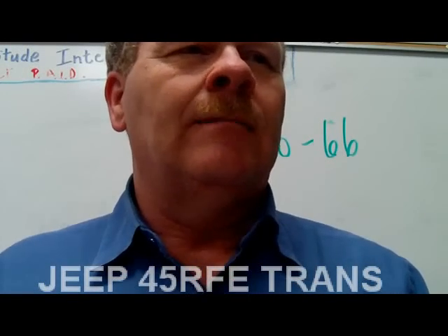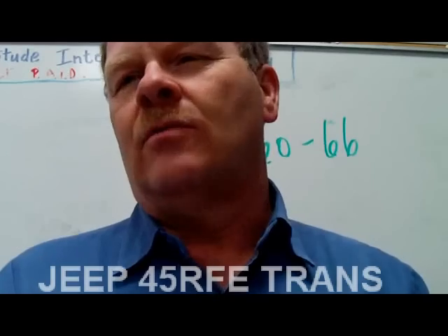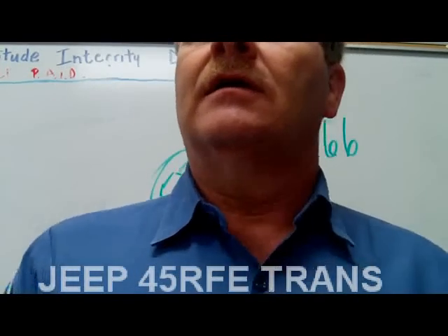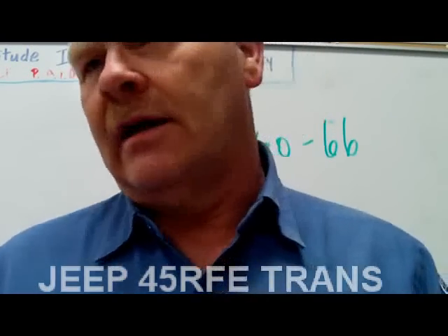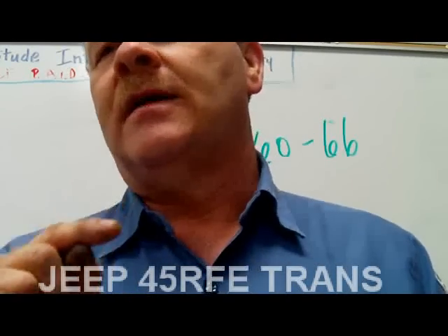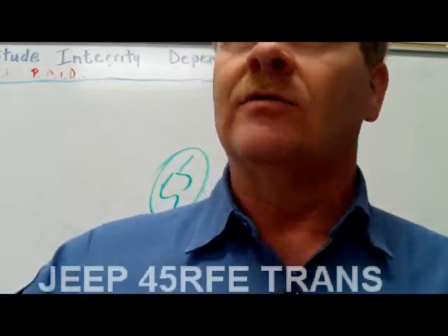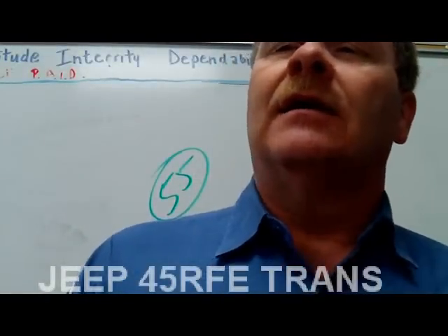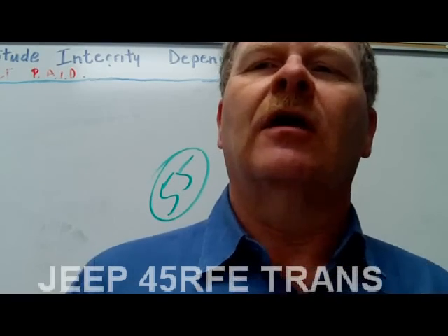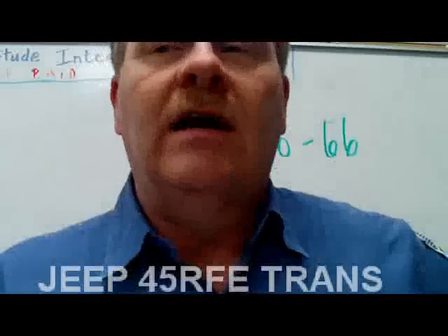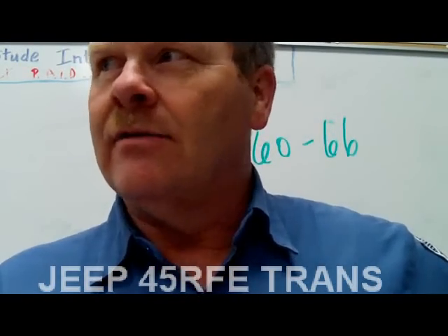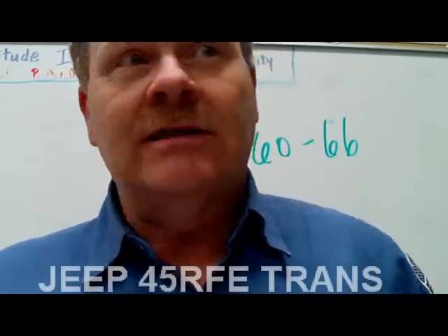Like the 4L60E transmission that you worked on in your truck: 4-speed linear, which is rear wheel drive, and 60 is the torque rating, and E means electronic. If it's a 4T60E, it's transverse, 4-speed transverse, like in the Oldsmobile. The odd thing is that Oldsmobile has a pretty substantial heavy-duty transmission because it's a fairly big car. That little 2005 Cobalt that we had in here, with that funky little 4-cylinder Ecotec engine, has a 4L60E transmission, just like that big Oldsmobile. That transmission is really a bear.